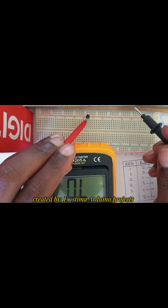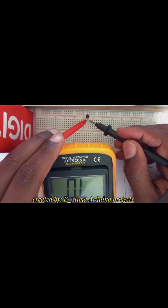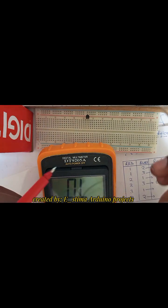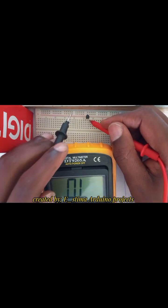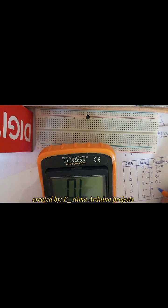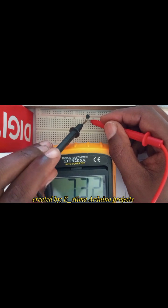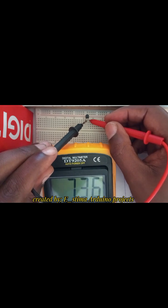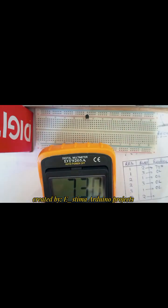Then we have 2 red, 3 black, no reading, and 3 on red, 1 on black. So we only have a reading when the red probe is on pin number 3 and the black one on pin number 2, which is 730.